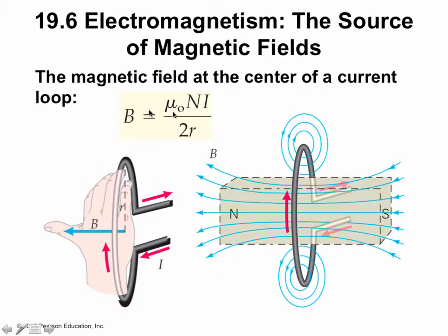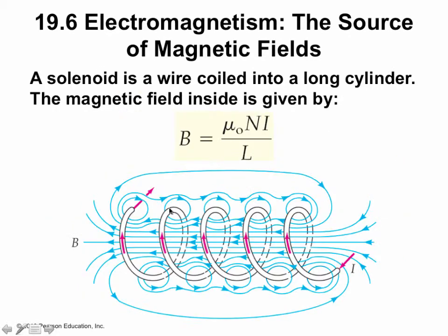We could calculate this magnitude by taking that same permeability constant of free space, multiplying it by the number of loops, times the current, divided by 2 times the radius of the circle. Well, the formula there, I said it wrong. But really what's going on is there are a bunch of little magnetic fields that go all the way around the loop. Notice that these magnetic fields rotate around this way, and over here these magnetic fields rotate around this way, and so it has an effect of a magnetic field that rotates this way. Does that make sense?